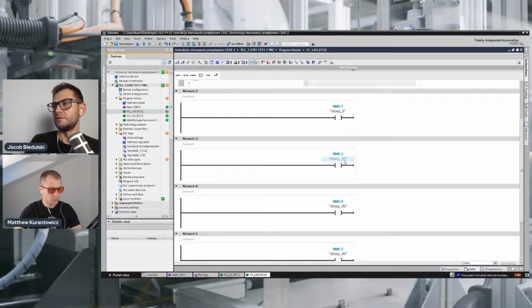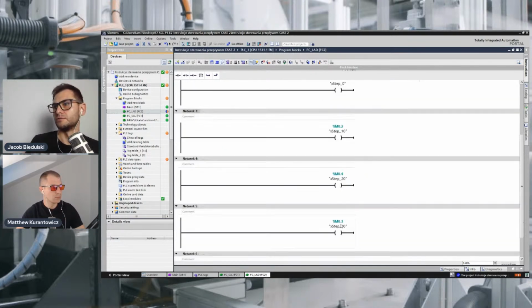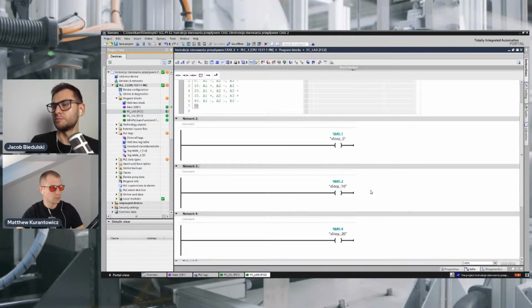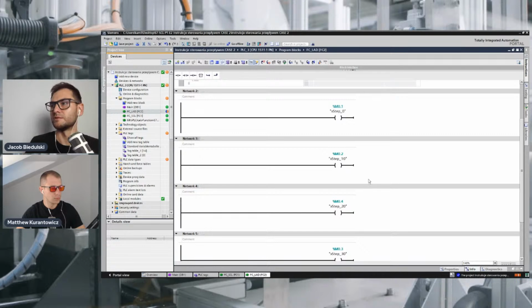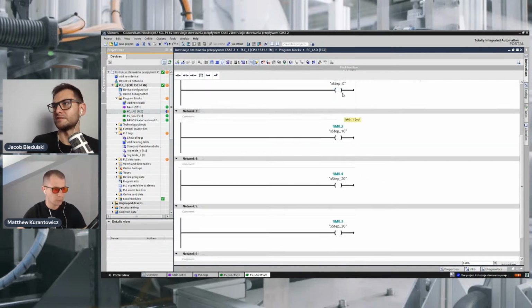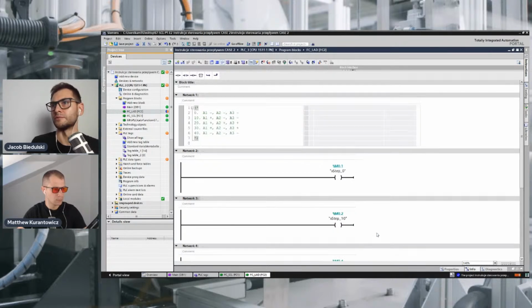Because if you want to modify your sequence, you can easily add another step. Between 10 and 20, you can declare 9 different steps, and you can modify your sequence easily. If you would use only 0, 1, 2, 3, there would be no simple number which you can use to add auxiliary steps. So we usually declare steps like 0, 10, 20, 30, and so on.